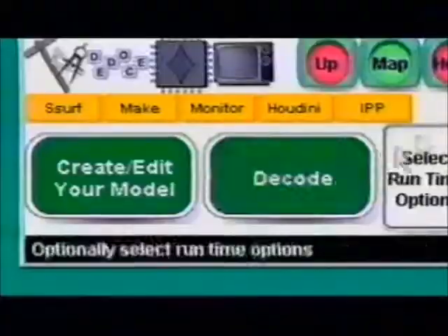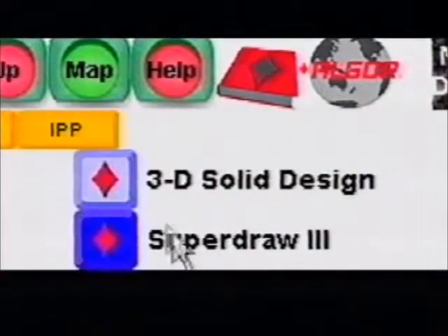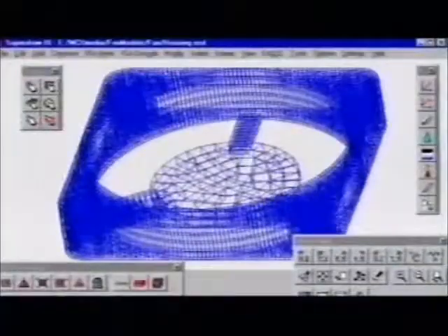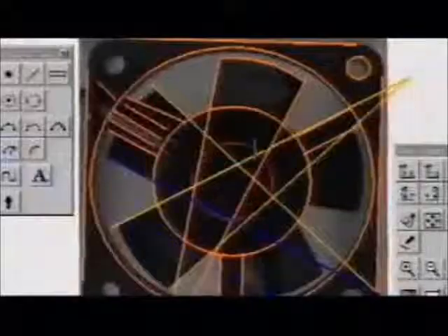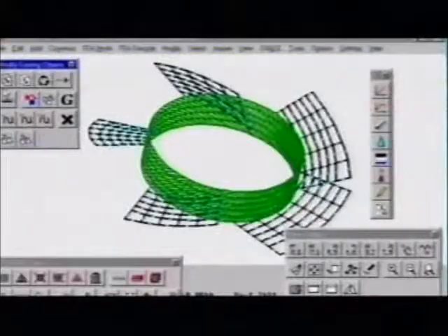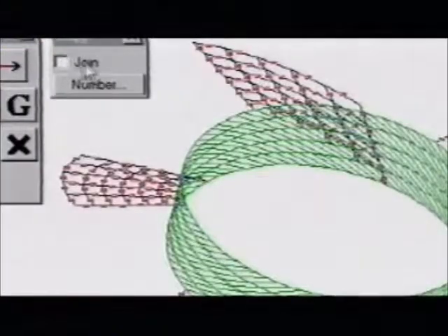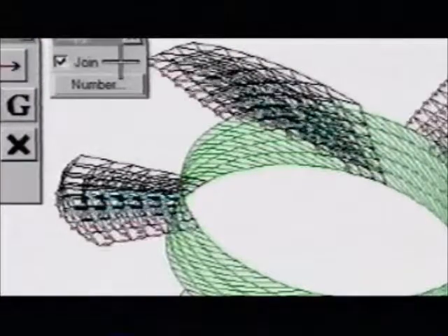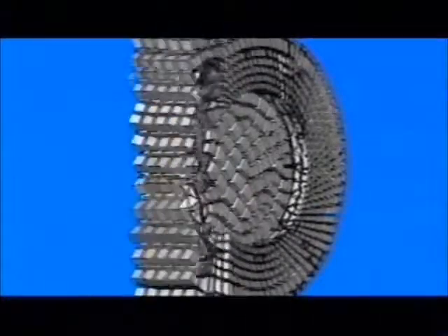The finite element model of the blade and housing was made in Algor SuperDraw. The real fan was photographed with a digital camera to produce a bitmap. The engineer used a tracing function in SuperDraw to construct the blade geometry of the model. SuperDraw needs only a few mouse clicks to create the mesh around the blades. Next, a surface mesh of the remaining volume was automatically generated and fitted to the previously created mesh. Algor Hexagon made the 8-node brick mesh, connecting the blades and support.